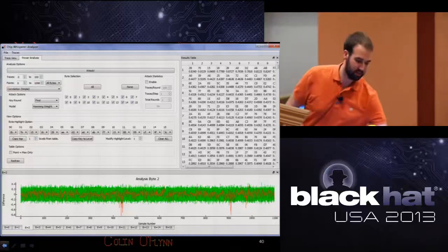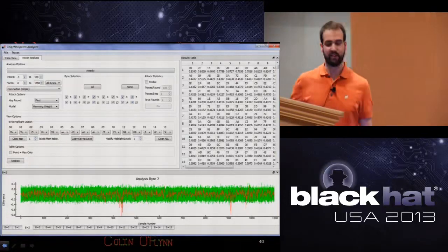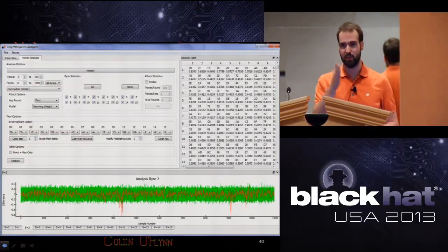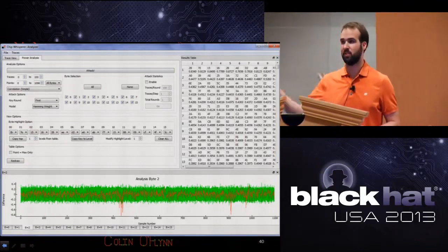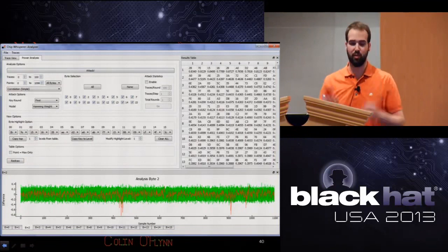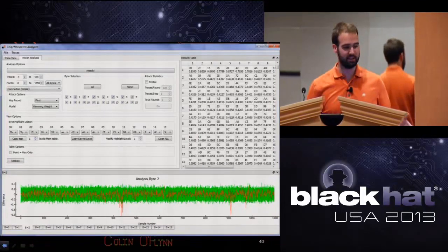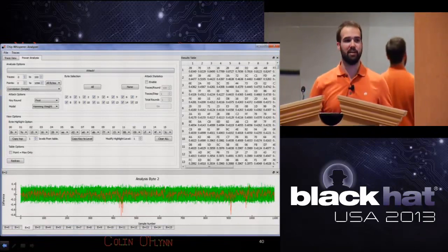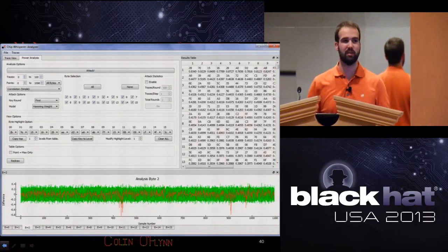If you're doing a cell phone that maybe is running at hundreds of megahertz, and it's doing the AES in software, you can get away with a pretty slow capture because it's not doing something every clock cycle. So you don't necessarily need to measure every single clock cycle on the data. You can average over a bunch. It's really highly dependent on the hardware. But the idea of the synchronized capture also is that worst case you would have to buy a faster ADC, which still isn't super expensive. You can get a gigahertz sample ADC for a few hundred dollars.